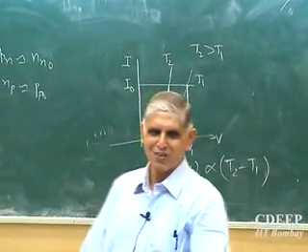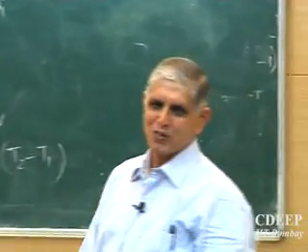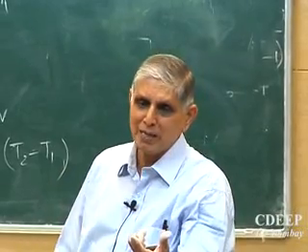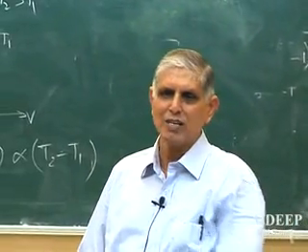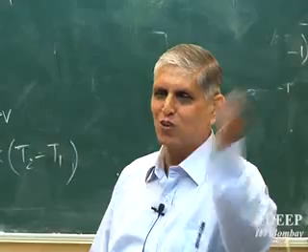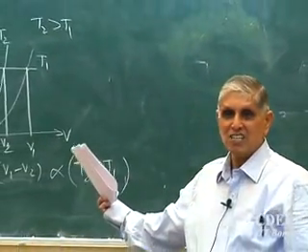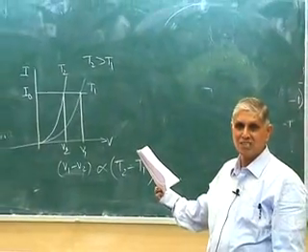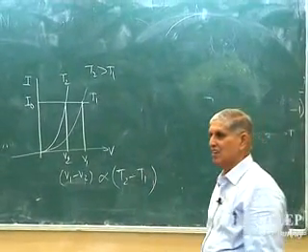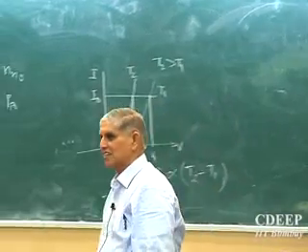So I monitor voltage. It's proportional. That constant I can find by measurements or by calculation. I can even directly solve it, you know, 2 equations, 2 unknowns. I can always evaluate that. This is essentially a thermal sensor. So a diode acts like a thermal sensor.